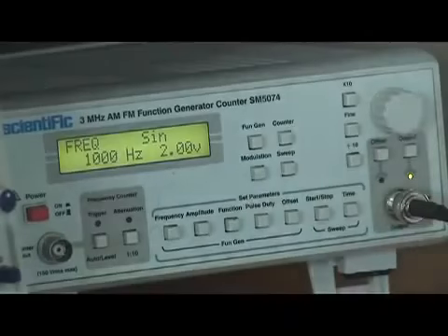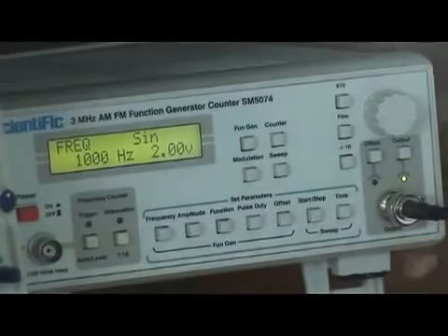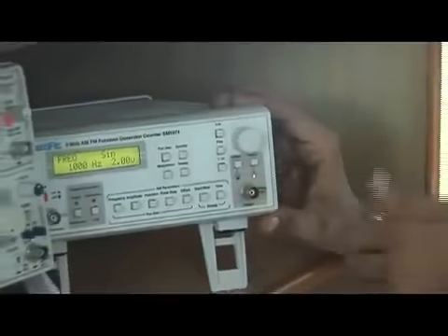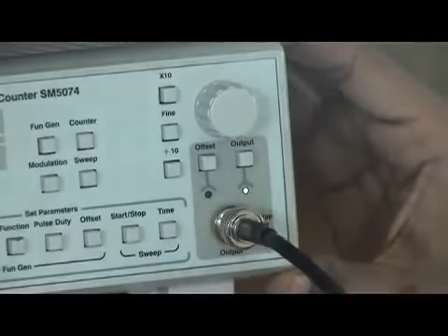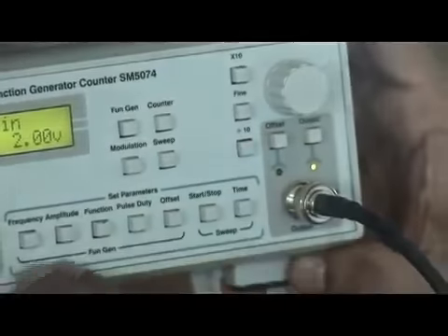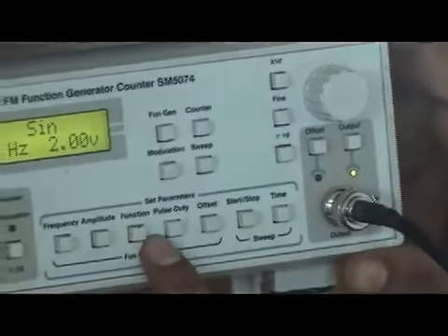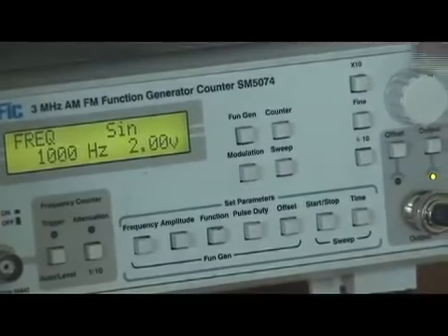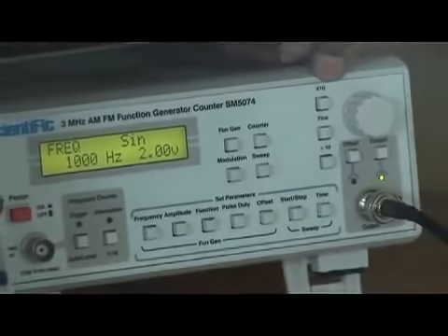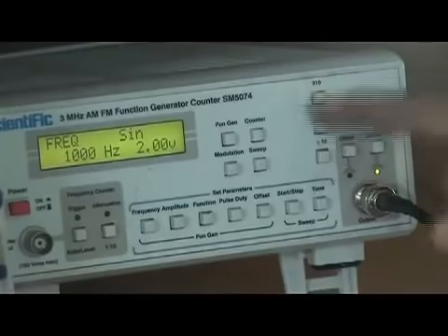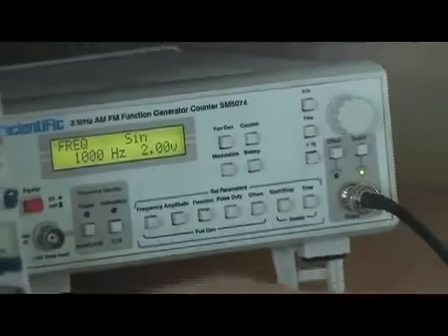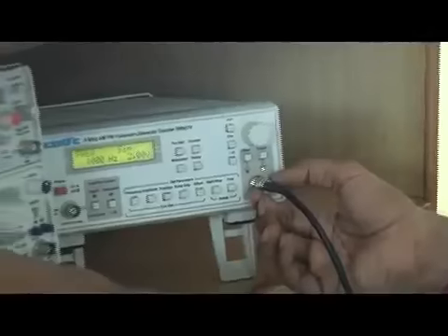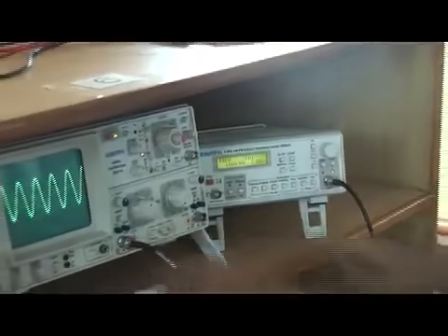Now I will connect from this, written as output. I will just open it for your convenience. It's written output, means whatever is generated here will come out from this output. I connect here and will go through this wire. So the important buttons in this function generator are frequency, amplitude and functions, and to vary the frequency or amplitude, use this knob. To multiply the amplitude or frequency by 10 or divide it by 10, you can use these two. So now the signal generated from the function generator is coming through this CRO cable, which has a two-side BNC connector. One connector I connect here, and the other connector I am connecting to the CRO.